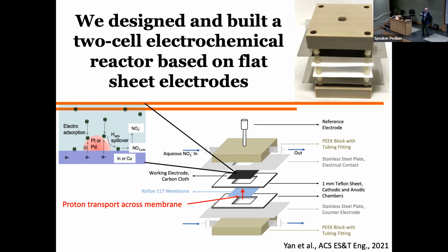They got great names. But in one case, even though your flow in is steady, because of the capillary forces, you get these pulses of liquid that move through there. And so we did try different flow regimes. And through all the flow regimes, the best results that we got are what I'm showing for the trickle bed reactor. For the very small reactor, I don't think it's necessary, and I don't think you'd see any real improvement by pulsing it. If on a larger scale we design this bigger reactor, maybe that would change. I don't know. It would depend on the situation, so I can't answer that.